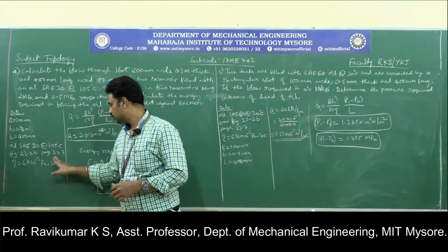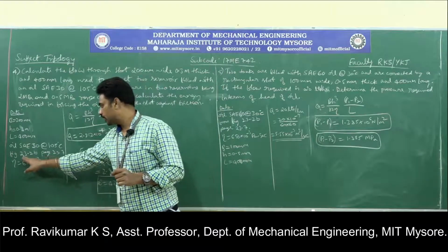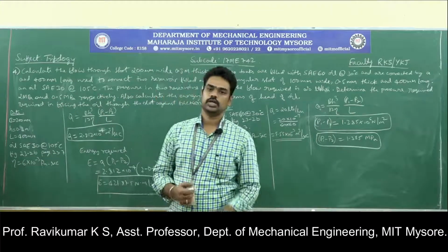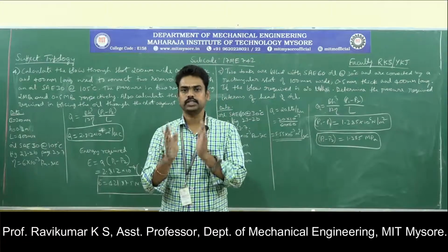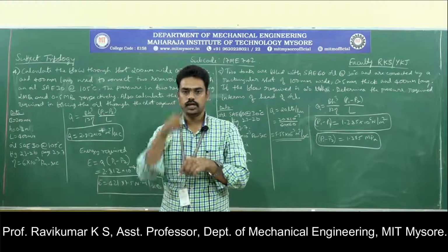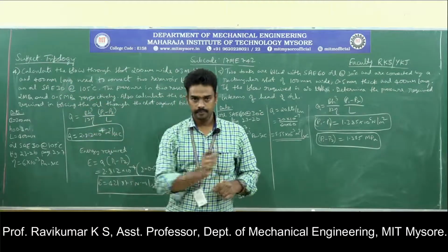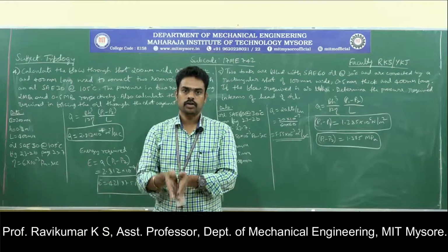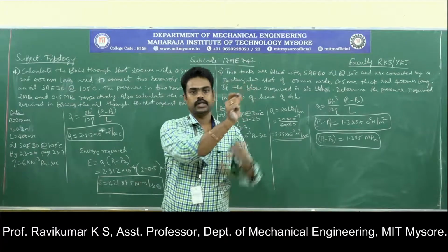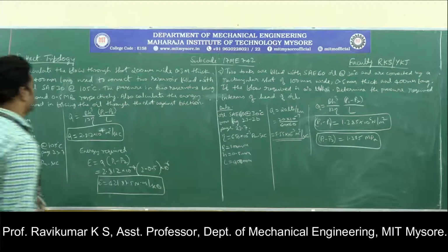On page number 23.7 in your data handbook, figure 23.2b, you will be able to get the viscosity. It is exactly like the stress concentration charts. There will be curves and boxes. You need to select SAE 30 oil, and temperature will be given on the x-axis. So match the temperature 105 with SAE 30 and take it to the left-hand side. On the y-axis you will get the viscosity. That is how I need to get the viscosity from the chart.